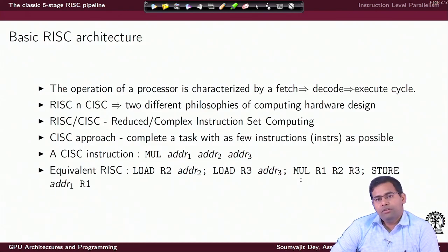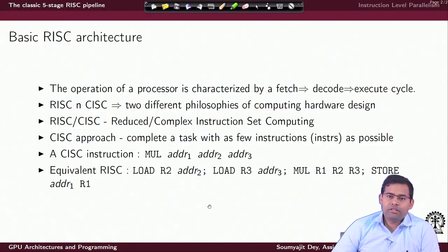As we can see, this multiply instruction takes as arguments the contents of registers R2 and R3, multiplies them and stores the result in the register R1. Now, this will be succeeded by the store instruction, which will store the result from R1 back to the memory address 1. So, essentially this summarizes the RISC philosophy, that all kinds of operations, specifically arithmetic logic operations, they have to